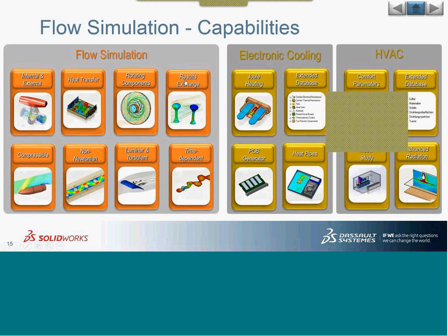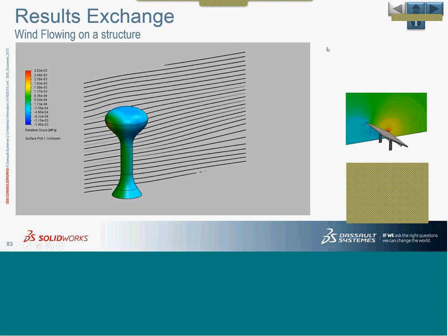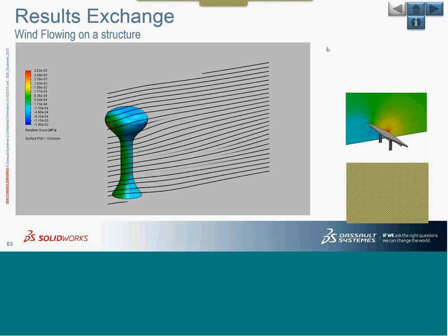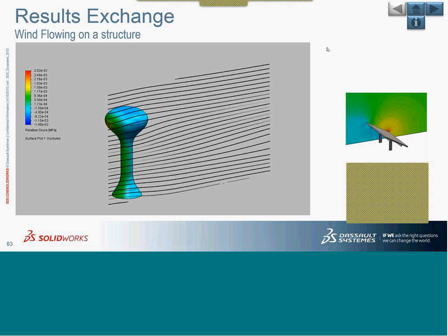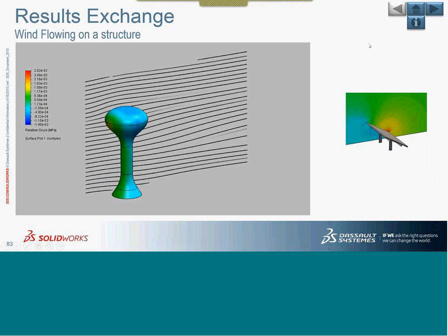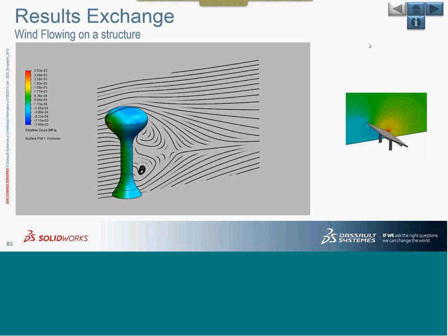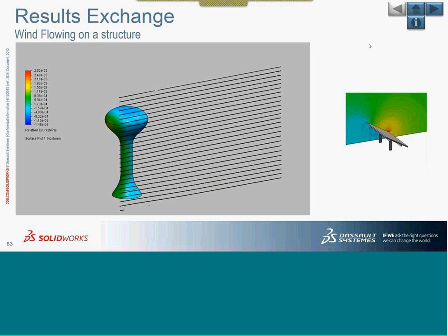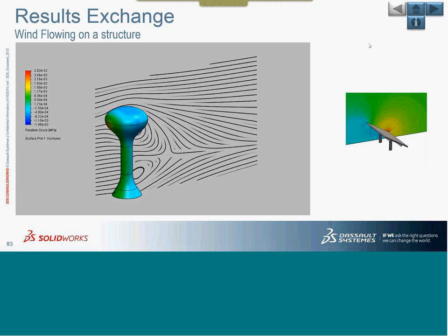So one final thing which is relevant in terms of broader level application of flow simulation is results exchange. We are actually taking results from flow simulation to structural or FEA. Those can be only two things. One is pressures which liquids exert on a structure. So that is one thing. Second could be temperature. Now it may not be temperatures, but what we are talking about is convection.